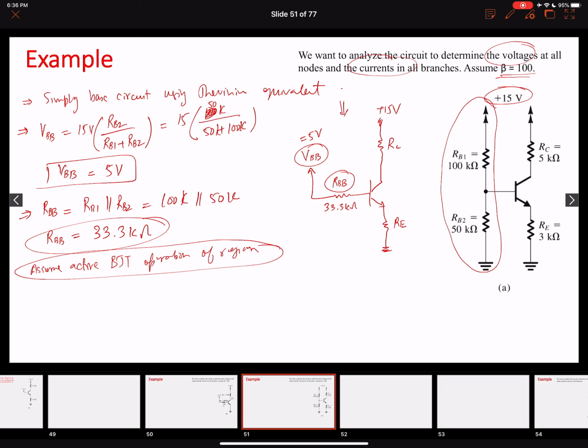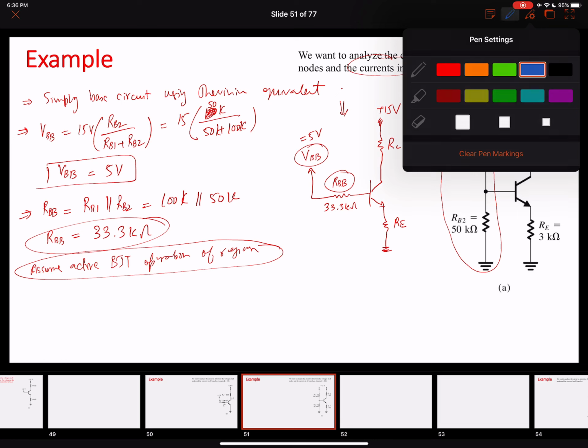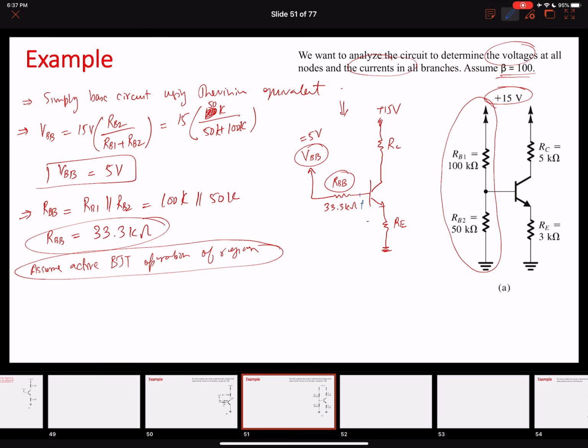Okay, so I know that the value over here is plus minus VBE, and the base current is flowing over here, IB. All right, so let's consider this loop. If I solve for this loop, I can write down this equation: VBB equals IB, the base current, into RBB, plus VBE, plus IE RE. Now I need to solve this equation to find the value of the emitter current.